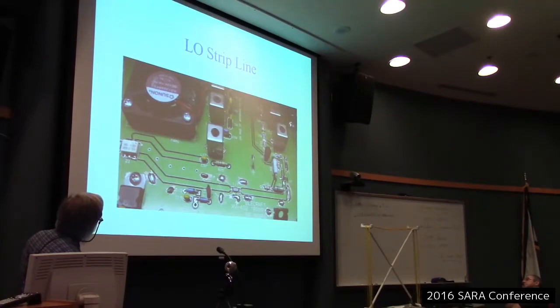And this is another thing that needs to be done with microstrips. You've got this grounded copper running right next to a microstrip trace, and this copper should be grounded at a lot of points along here. I've heard of an example from Charles about, I think it was a 10 gigahertz RF switch or something, that 4 of them on a board, 2 of them worked and the other 2 didn't. They appeared to be identical layouts. And the whole problem was these little via holes which connect ground from the top to the bottom weren't there.